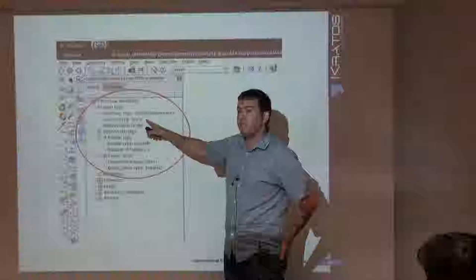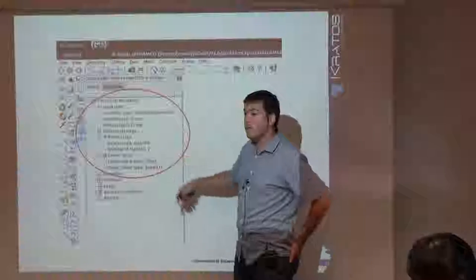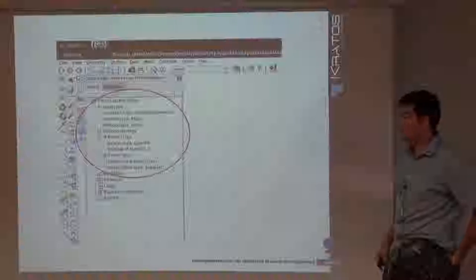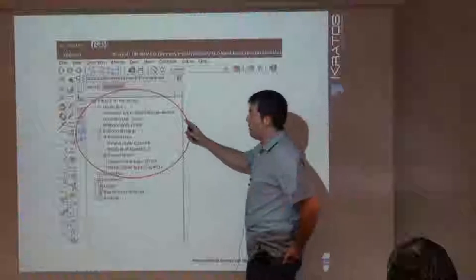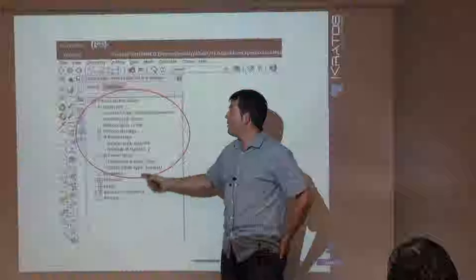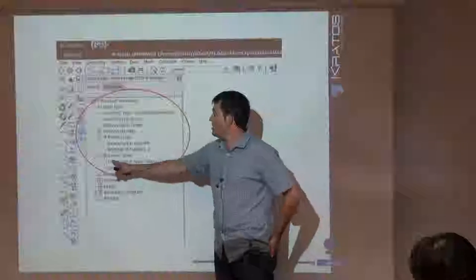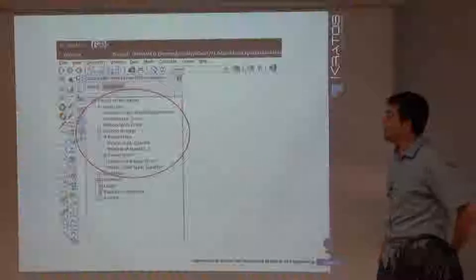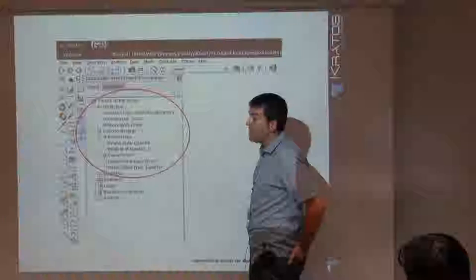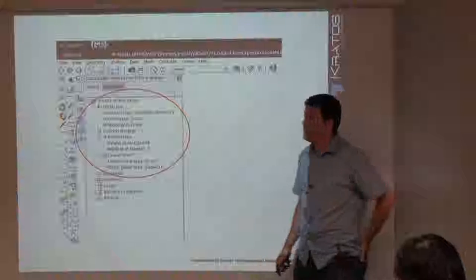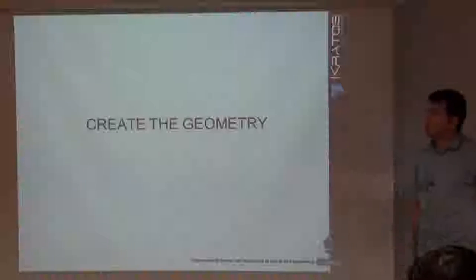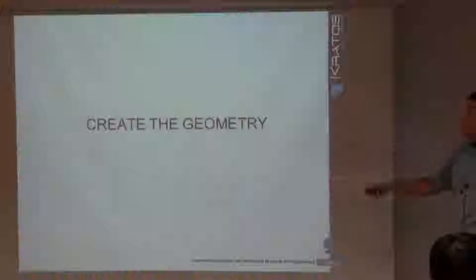If we are selecting dynamics instead of static, then we can select if you want it implicit or explicit, right? And if we select dynamics, we will see later appears just another line here that allows you to select which is the time step that you want to use and which is the total time of the simulation. So first thing in the finite element program, create the geometry.